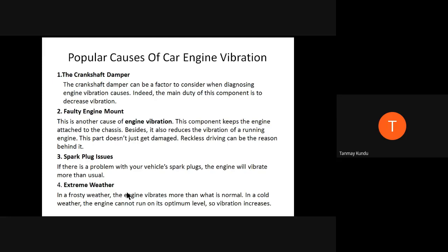Obviously, the vibration problem will stay on the engine. So occasionally you have to check whether the crankshaft damper is all right or has been worn out. This is point number one. If the damper is non-functional or worn out, the problem of vibration may stay in the car engine.